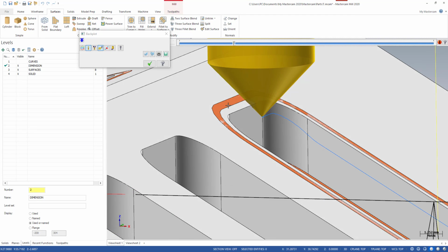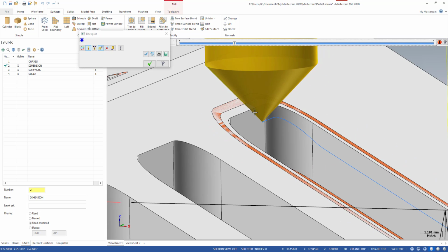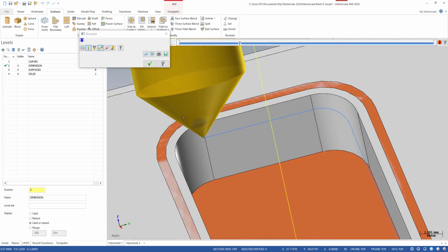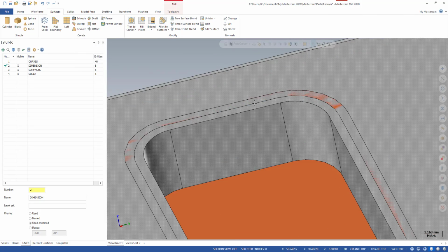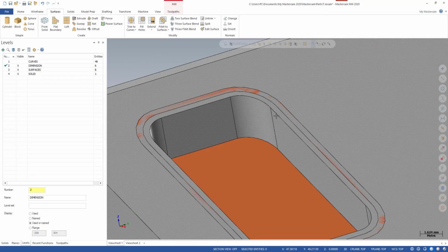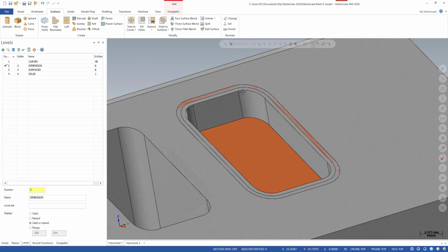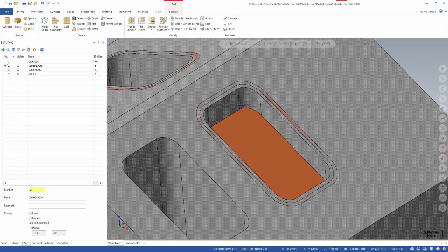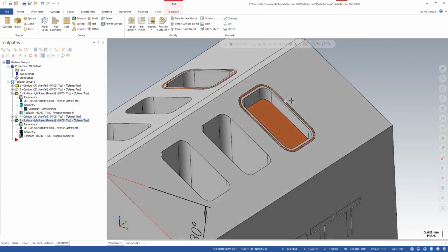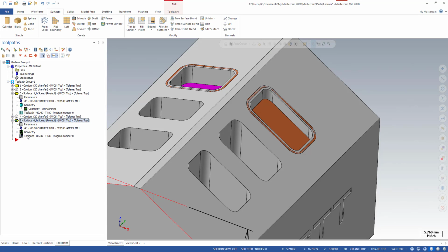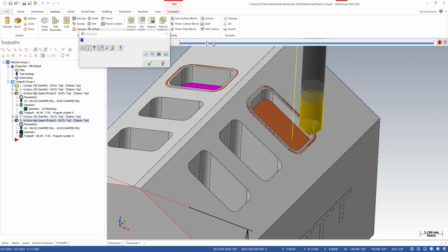So that's how we make a constant chamfer. You can see the distance between this edge to the surface is constant. I make it 0.5. Okay, that's how I can control the toolpath. Very easy, right? So how I did it.